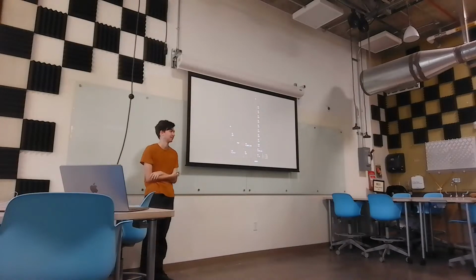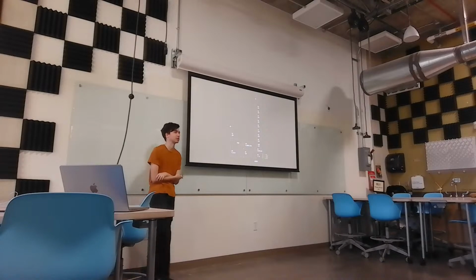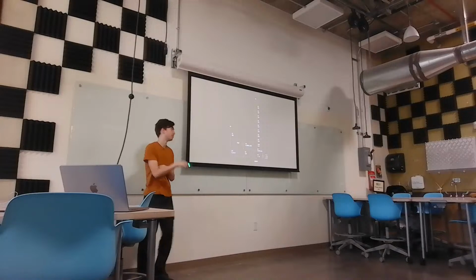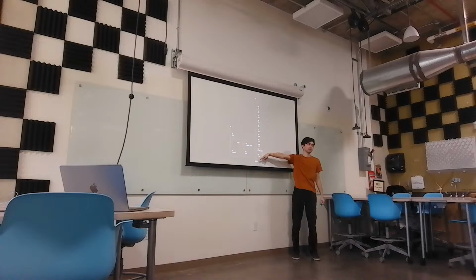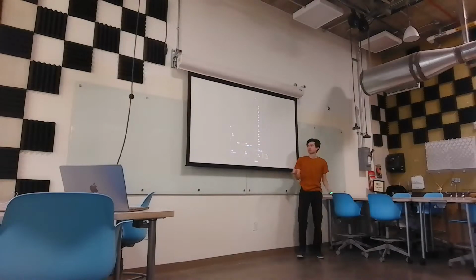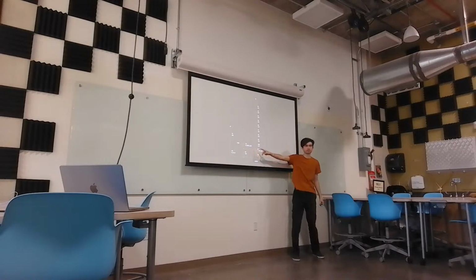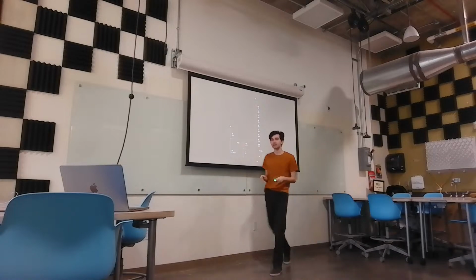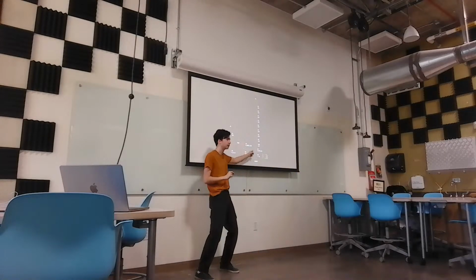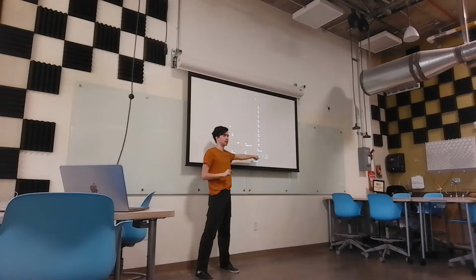It's linearly proportional to the current going from the base to the collector. So I think what you're looking for is that the current going out of the transistor down here is equal to some variable beta times the current entering the transistor here. The second equation is that the sum of this current and this current equals this current. The currents are coming together and all going out. So what we get from that is that a very, very tiny current coming in here can result in a very large current coming out here.